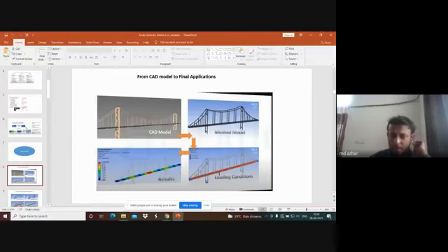So again, you can see in this that this is the start of the bridge. At the start of the bridge, you largely have blue areas. The contour is showing equivalent stress. So the equivalent stresses acting here are very small. However, as you move forward and come to the middle of the section, the equivalent stress becomes large. So this part is subjected to high equivalent stresses.